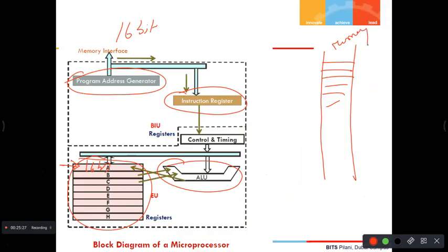I told you that suppose this is an 8-bit memory. 8-bit memory means in each location you can save how many bits? 8 bits. I already told you about this in my previous class. Now this is address 0000. Suppose if this is 1 MB memory, you will have a 20-bit address, which will be represented by hexadecimal digits. I'll tell you about all these things. This next location will be 0001. Next location will be 0002, like that. The last location will be FF in hexadecimal.